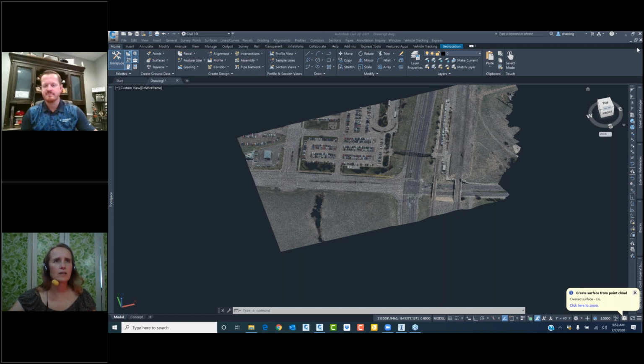Okay, and I love this. JVeal81, and I apologize, I wish I knew your real name, but that's the handle in the forum, is saying, I've used point clouds in Revit in the past, and it's quite easy to link them in just like you would any other link. Bring them in on level 1, and in the model, the point cloud can be cut through sections and section boxes. So great, I love that.